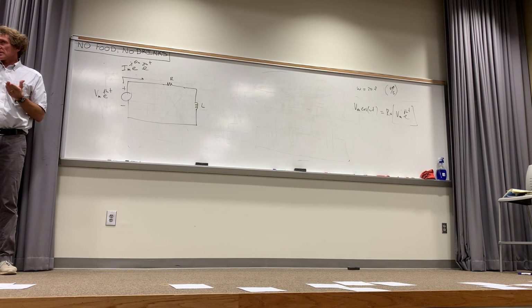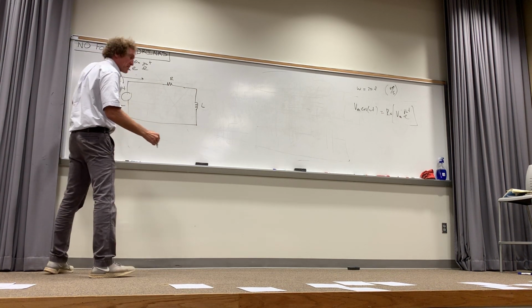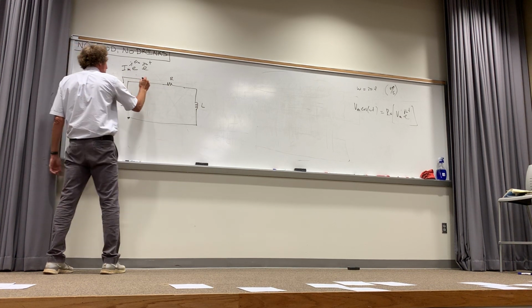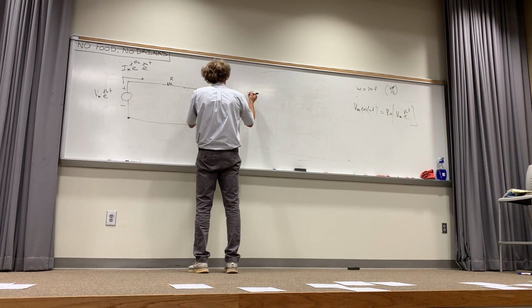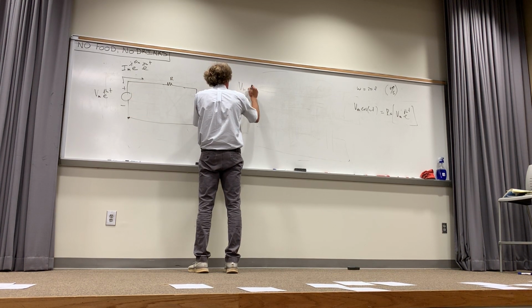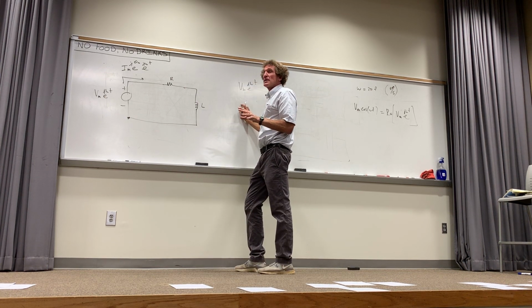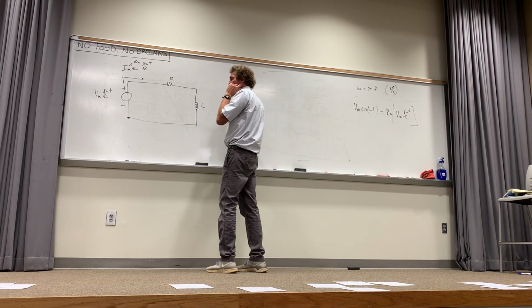Now just listen, and you'll get this. That's the source voltage, right? We're going to do voltage drop starting here, and I'm going to go around here. That's my current going this way. So if I come from here to here, I get a voltage increase of Vm e to the j omega t. All right. Now this again is usually what's called a phasor notation, but believe me, I'm going to show you how it reduces the problem's complexity into just algebra.